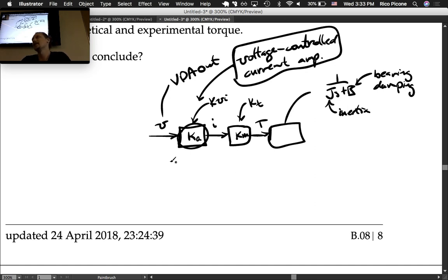But with AC, a lot of times the existing thing that was there that only had one speed is an AC motor, and then trying to retrofit control to it is hard. You can use these VFDs, which is your only real good way to go with it.